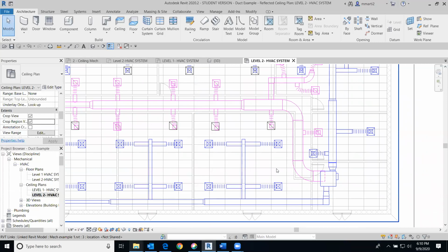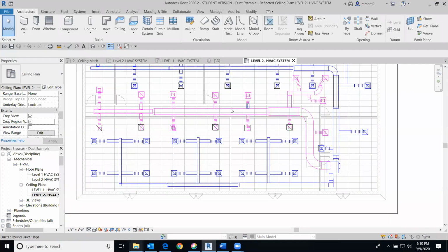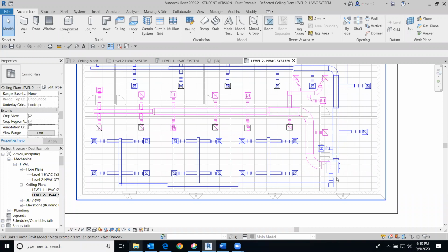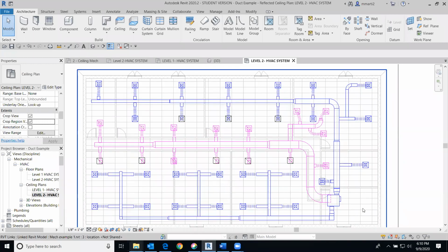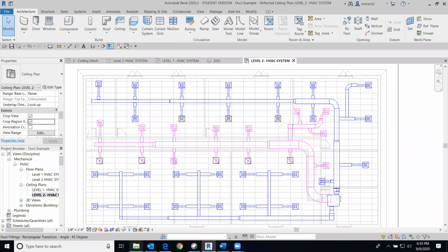And one of the things that we have in this drawing that we didn't really talk about too much was the use of smaller and smaller vents as we go along. And this is really what we're looking to do when we're laying out our ductwork. The idea behind that is we start with these larger ducts, and if you look at some of these duct systems, in the larger ducts you're going to have more airflow pushing through, and it's going to constrict the further along it gets in order to continue that air capacity from this spot right here.